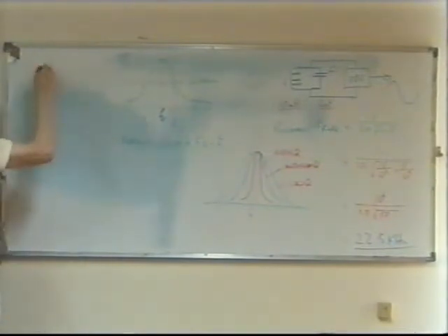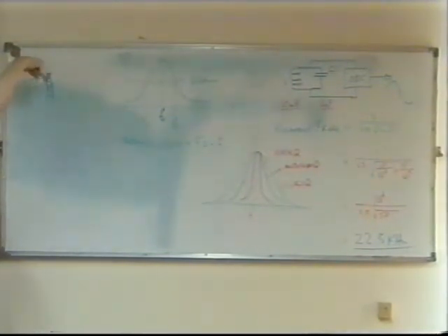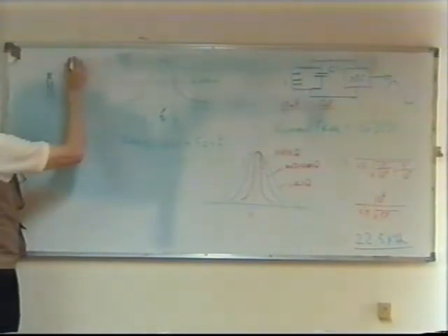Sometimes in the middle of this tube they have what is called a slug, which has a thread on it, which when you turn it goes into the tube. That slug has an effect on the magnetic field. It can increase or decrease the amount of magnetism and therefore change the value of L. The circuit symbol for that would be something like this.